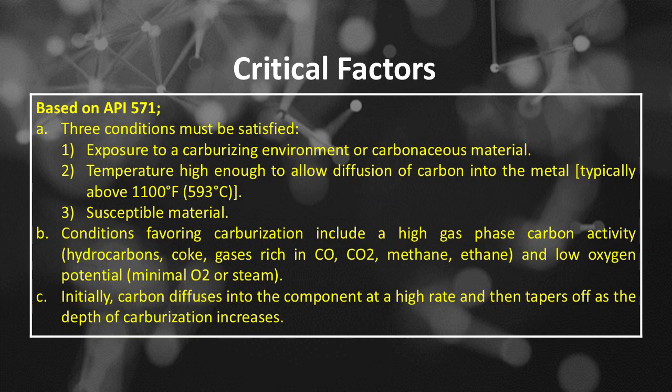Carburization damage critical factors based on API 571. Number A, three conditions must be satisfied. Condition 1, exposure to a carburizing environment or carbonaceous material. Condition 2, temperature high enough to allow diffusion of carbon into the metal, typically above 1100 degrees Fahrenheit or 593 degrees C. And condition 3, susceptible material.